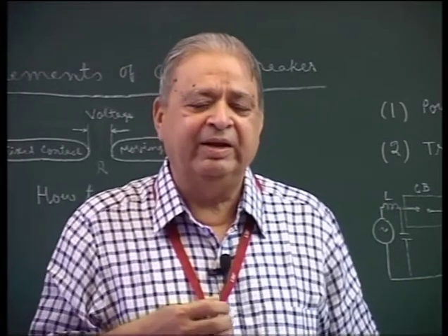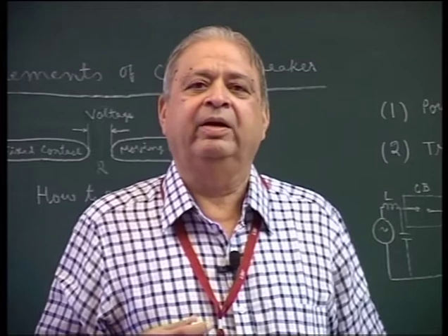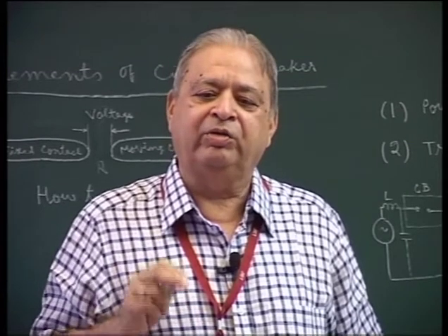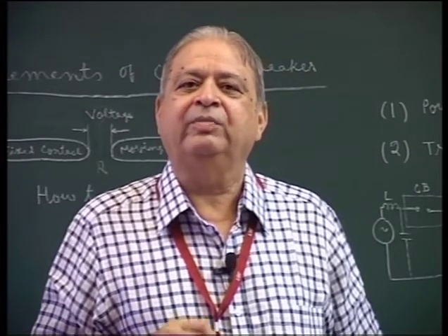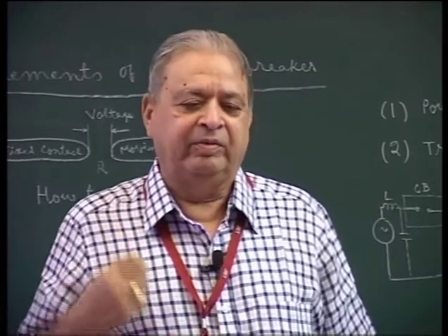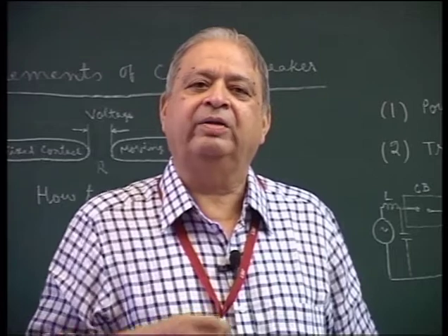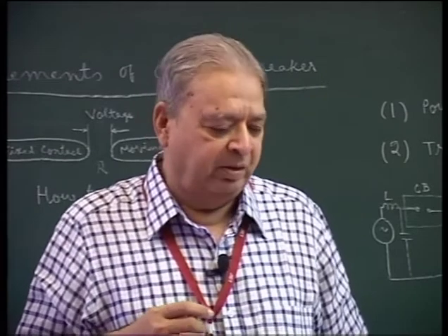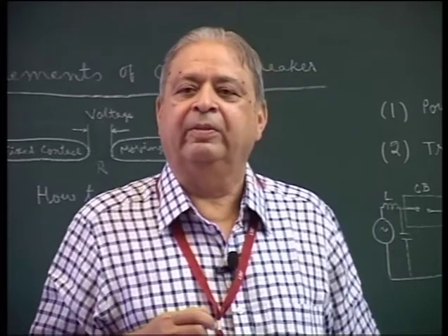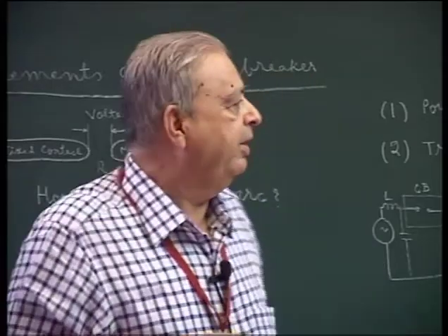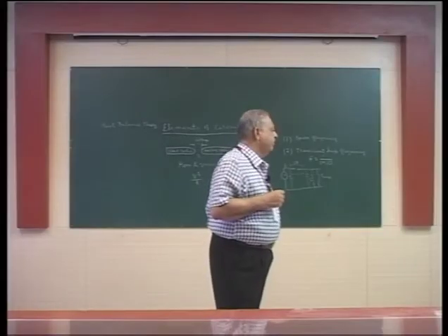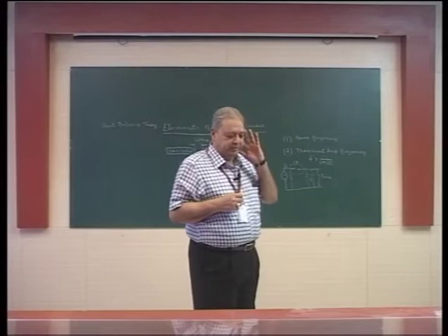But mathematically, if we calculate and apply it to particular circuit breakers, then in some circuit breakers the heat balance theory gives better results, and in some circuit breakers the rate of rise of restriking voltage theory gives better results.